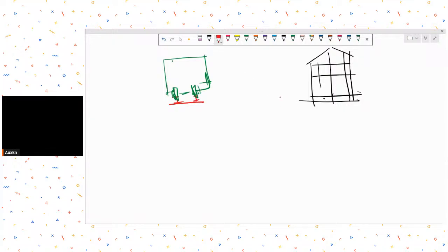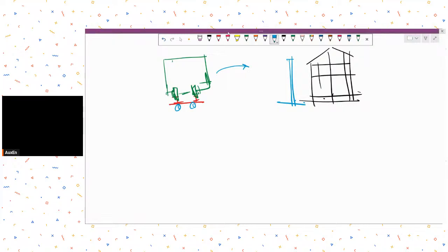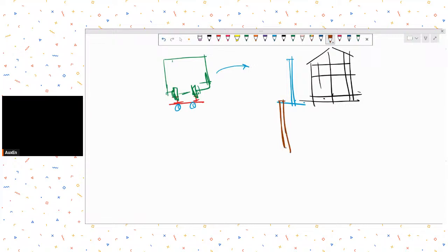One vibration will be due to the sound, which you cannot safeguard your building from. If sound is a problem, then you will have to think of erecting some barriers. But if the vibration from the railway track is a problem, what I can think of is to go for some sort of isolation. Isolation can be that you provide some retaining wall type of a thing. So let's say this is some ground, this is your natural ground.